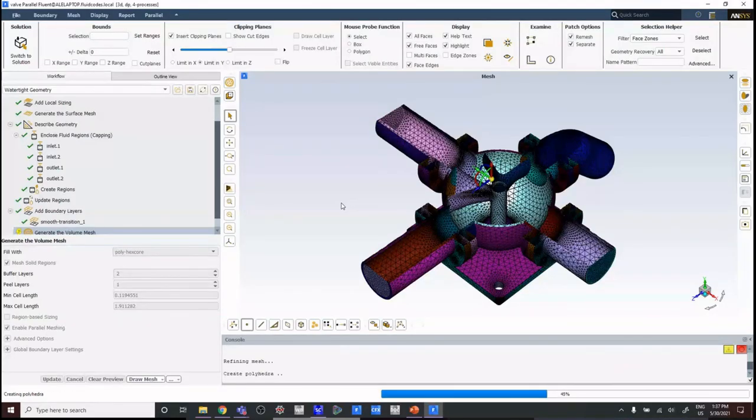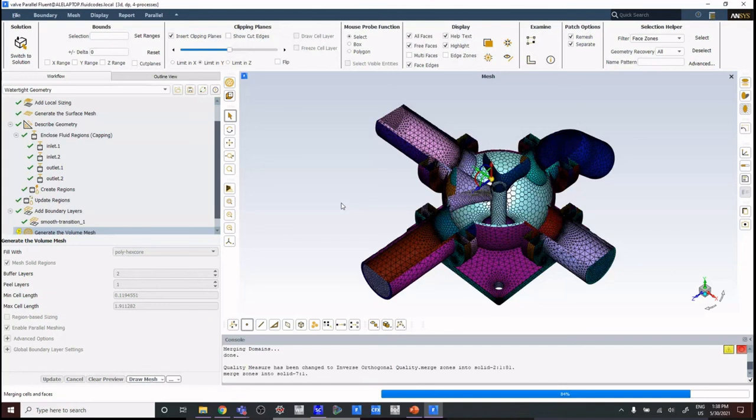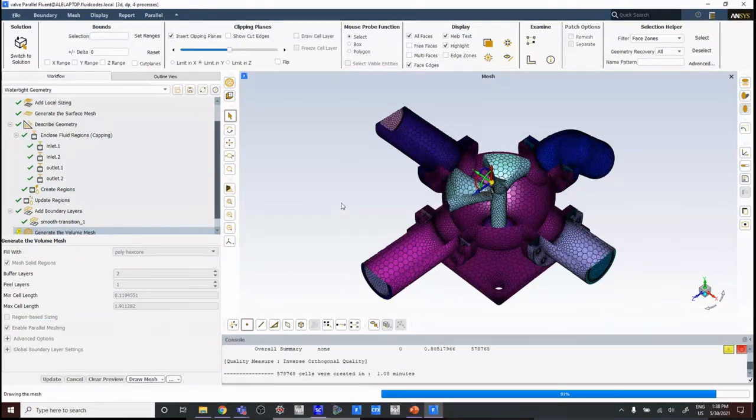Okay. So the first question is, are there any tutorials to help learning Spaceclaim meshing? There should be something. Yes, we can share that. Right. Second question is, depending upon the problem, does Ansys automatically select the meshing options like Fluent or Spaceclaim or TurboGrid? Not really. This is an input that has to come from the user because they are completely different tools. So we need to specify what tools we want to use. So it's a selection by the user, basically. Based on the application, we pick what is the best one.